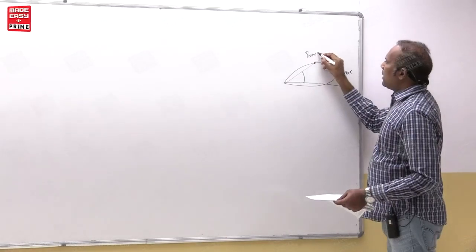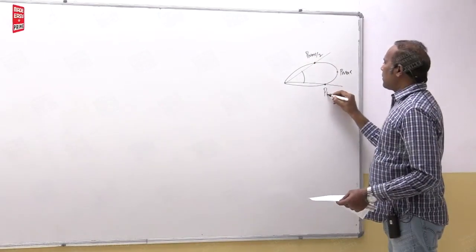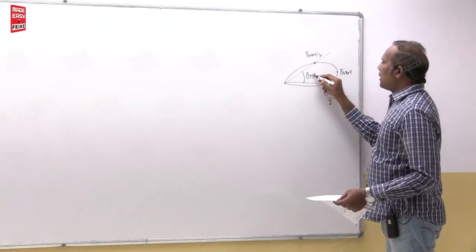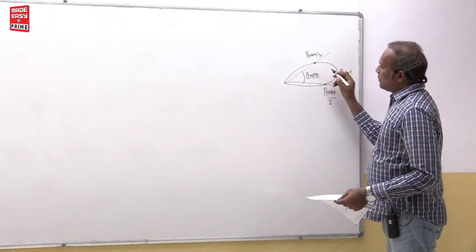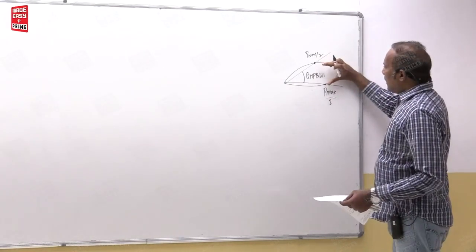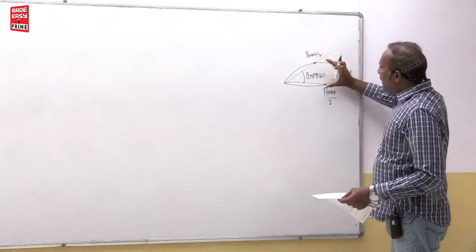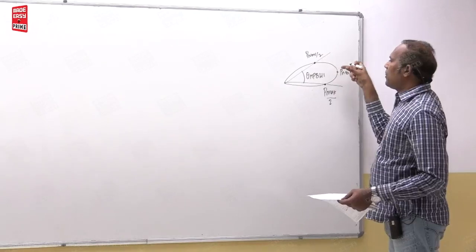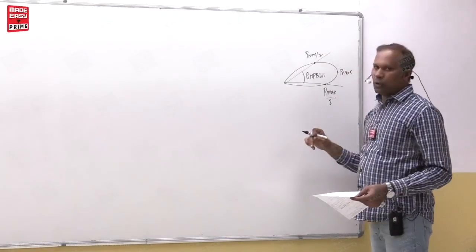So maximum power by 2. This is also maximum power divided by 2. Then this is called half power beam width in plane 1, vertical plane. Then 90 degrees to that vertical plane, in this direction how much beam width is there, half power beam width, that is half power beam width 2.